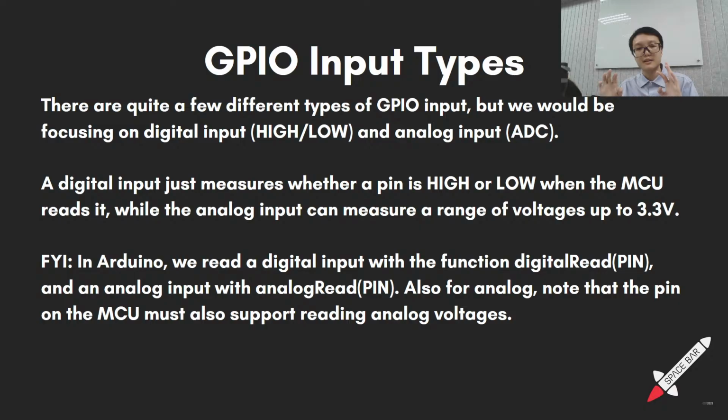So you can also configure GPIO to act as interrupt pins. What is an interrupt? An interrupt tells the CPU, or let's say the ESP32, when a predefined event occurs: stop whatever you're doing, service me now.